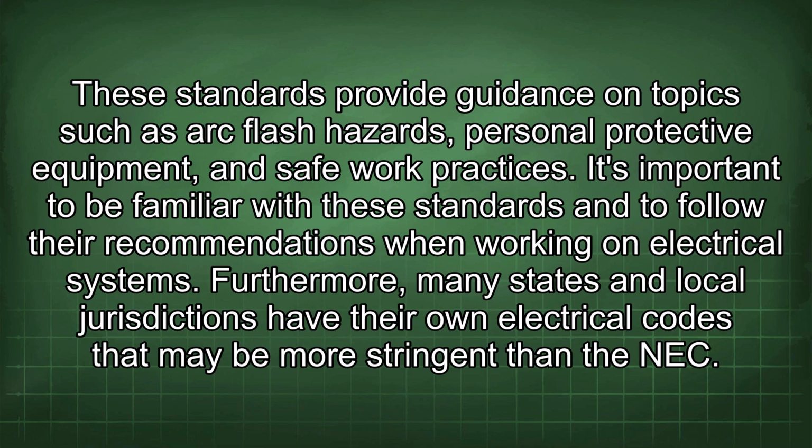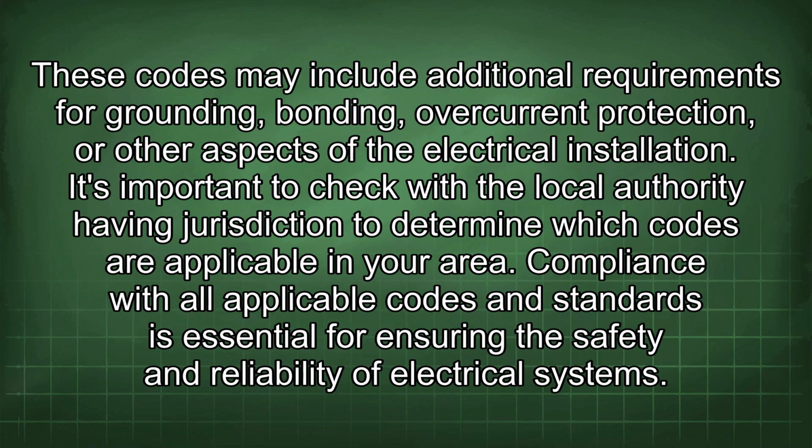Furthermore, many states and local jurisdictions have their own electrical codes that may be more stringent than the NEC. These codes may include additional requirements for grounding, bonding, overcurrent protection, or other aspects of the electrical installation. It's important to check with the local authority having jurisdiction to determine which codes are applicable in your area.